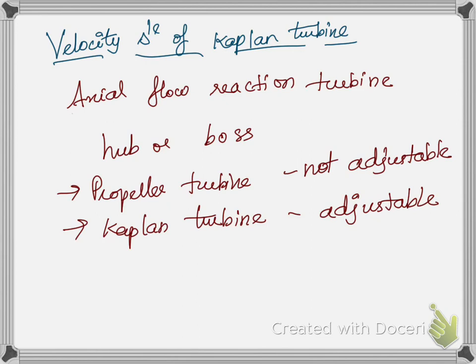Before going into that, we'll have a small introduction about the axial flow reaction turbine. If the water is flowing parallel to the axis of rotation of the shaft, then the turbine is known as an axial flow turbine. And during the flow of water, when a part of the pressure energy is converted into kinetic energy, then the turbine is known as a reaction turbine.